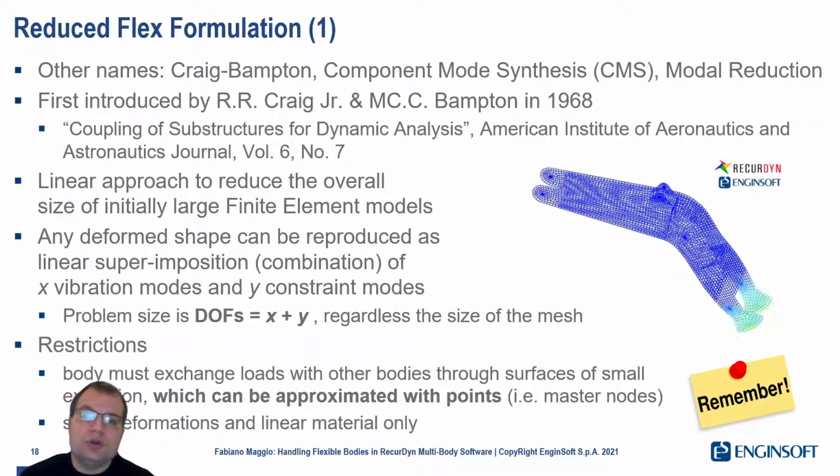The other approach, which is included in RecurDyn, of course we couldn't miss it, is the reduced flex. The reduced flex is known with many different names in the community: component mode synthesis, model reduction, Craig-Bampton method. All of them are different names, but the theory behind was invented by Mr. Craig and Bampton in the late 60s.